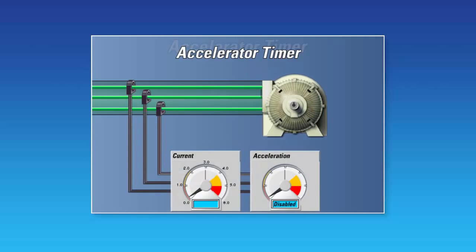When enabled, the acceleration timer trip element functions as follows. A motor start is assumed to be occurring when the relay measures the transition from no motor current to some value of motor current. Typically, motor current will rise quickly to a value in excess of the motor's rated full load current. At this point, the acceleration timer will start to time. If the motor's current does not fall below the overload curve pickup level before the program time has expired, the relay will generate an acceleration trip.